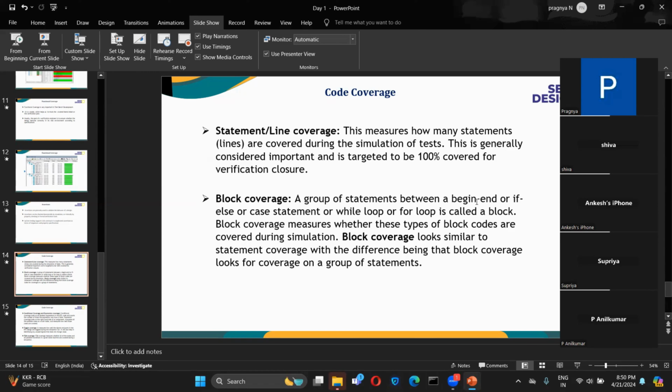We can think so, because a self-checking test bench is nothing but writing, for example, the scoreboard logic. What will we do in the scoreboard? We'll be trying to compare the expected data and actual data, right? The same thing we will mention in the particular test case itself. You will be writing some kind of checker mechanism, right? Likewise, this assertion also, but it has some different kind of things. We use sequences and properties, and this will be for all the tests also. It will be applicable if we include these assertions in our top level.